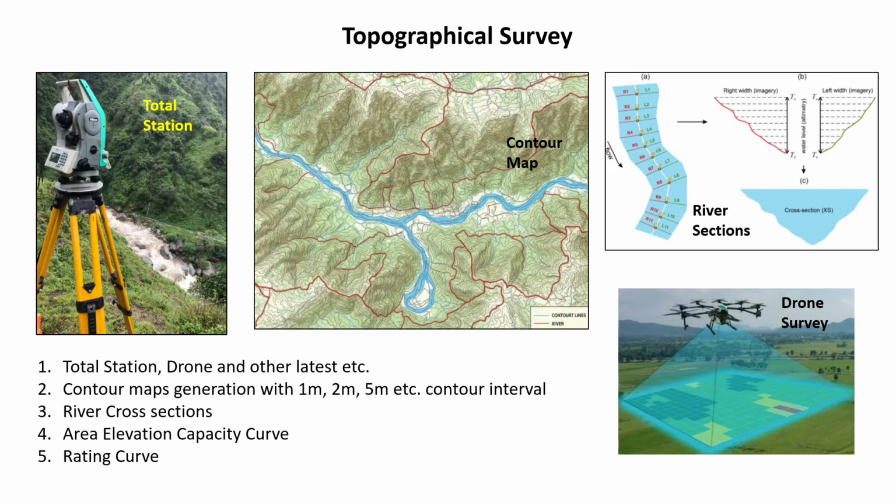Once we have finalized a dam site, then we will go for a detailed study at that place. We have to collect the topographical information. This can be done by conventional total station and other surveying instruments. Further, latest technology such as drone survey can also be used.